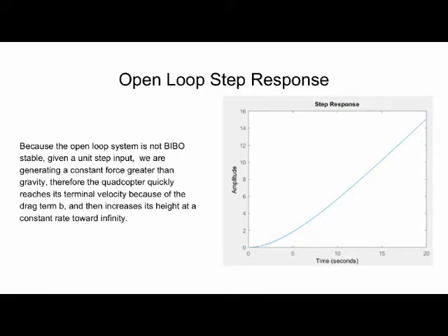The step response of our open loop system indicates that a small change in force is magnified in the behavior of our system. Due to this response, wind and change in mass have the potential to destabilize our final system and must be considered. Generally, landing is done in an open area where the force of wind is parallel to the ground, meaning that it applies a very small vertical force to the system.